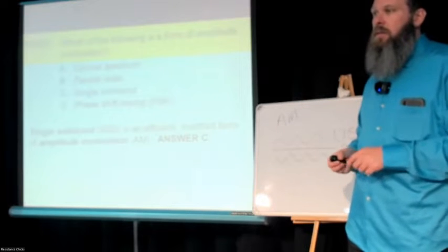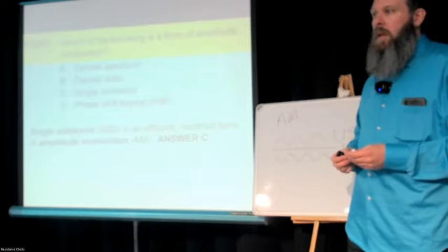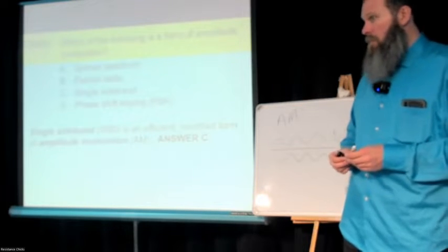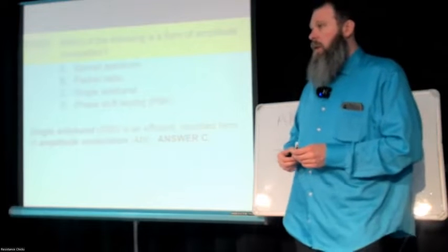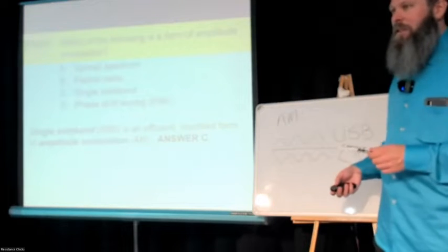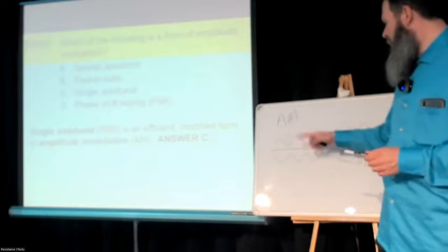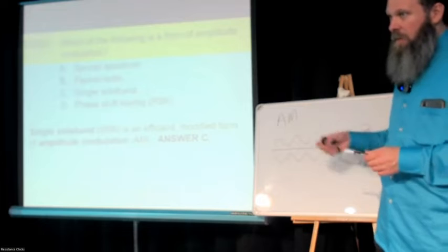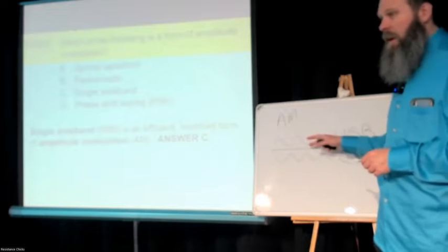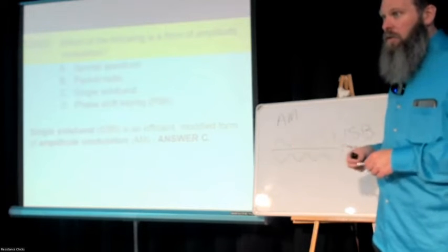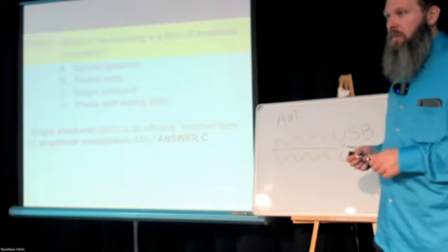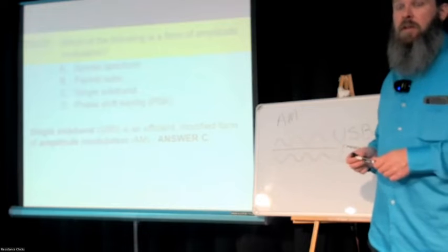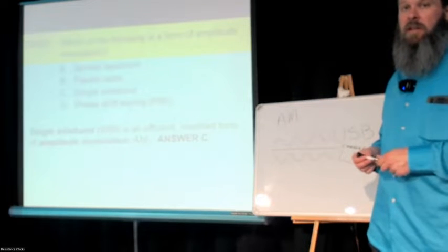So single sideband is cut down all the time? Yes. So it was an FM wave? No, it was an AM. And further reduced. That AM transmission would have had a carrier, the lower sideband and the upper sideband, and they would have eliminated the carrier and one of those sidebands. They just don't incorporate that within the modulation of the signal.